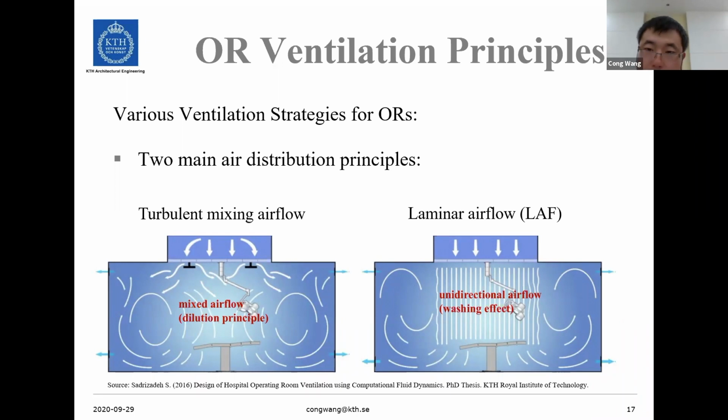Laminar flow ventilation, on the other hand, is a concept that we have borrowed from industrial clean rooms. Instead of relying on the dilution principle, it relies on the washing effect. The air is supplied along parallel streamlines at nearly identical speed with a high momentum. This downward airflow aims to directly wash away the particles from the surgical critical zone.